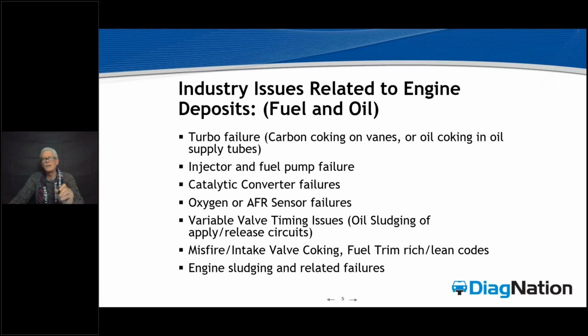But look at these things that we have on the screen right now and tell me that every single one of these aren't things that we do battle with, see, or diagnose every single day in our shops, okay? Every single day we're seeing misfires, lean codes, everything you're looking at here, converter codes, injector failure, high pressure pump failure on these GDI cars. Every single piece of this really comes back to proper lubrication, proper maintenance, and the reduction of carbon.